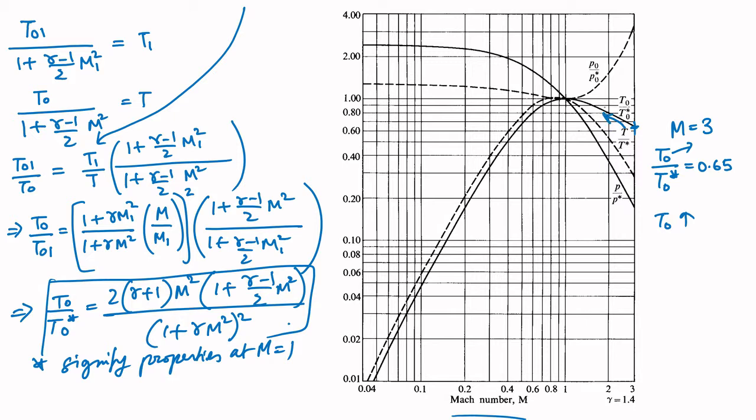Okay. So, as you are moving in this direction, what happens? You see your Mach number is dropping. So, as T0 goes up, your M is reducing, and you can show that for the T0 to continuously go up, it can only go up to this point.